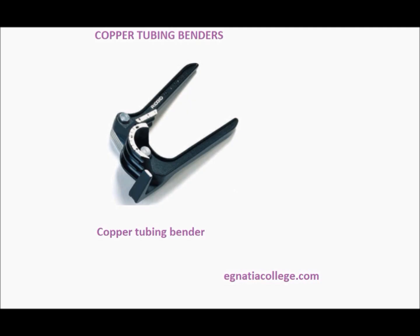Many tools serve pipe sizes ranging from 1/8 to 3/8, but others are for only one pipe size. The tubing is inserted into a grooved portion of the body, and the handle, which is also grooved, is used to manually achieve the desired bend. It will take practice to ensure accuracy of a bend.